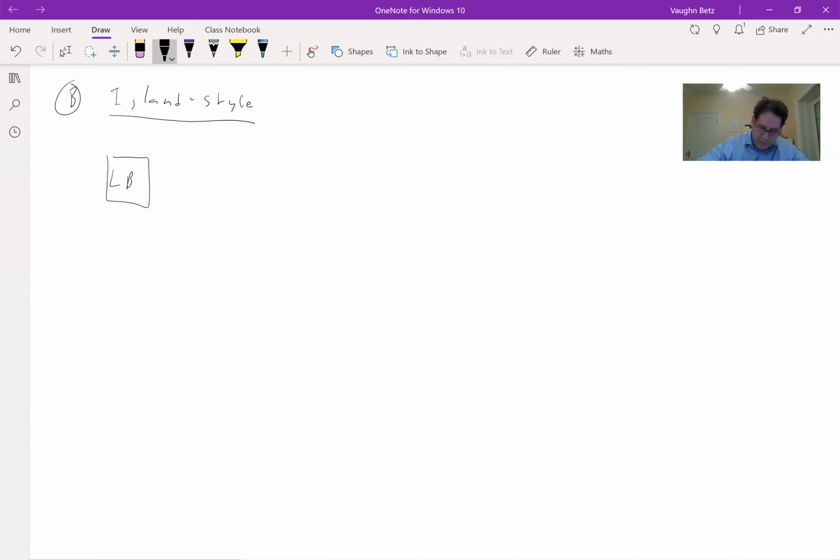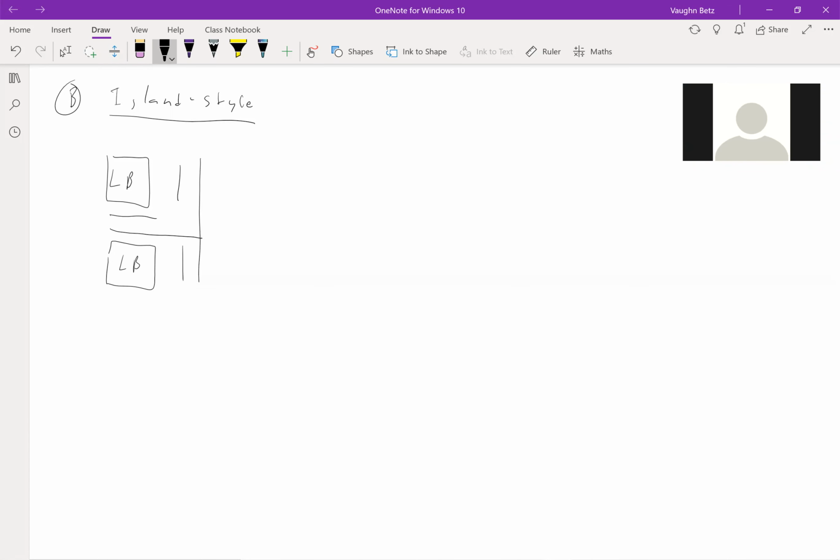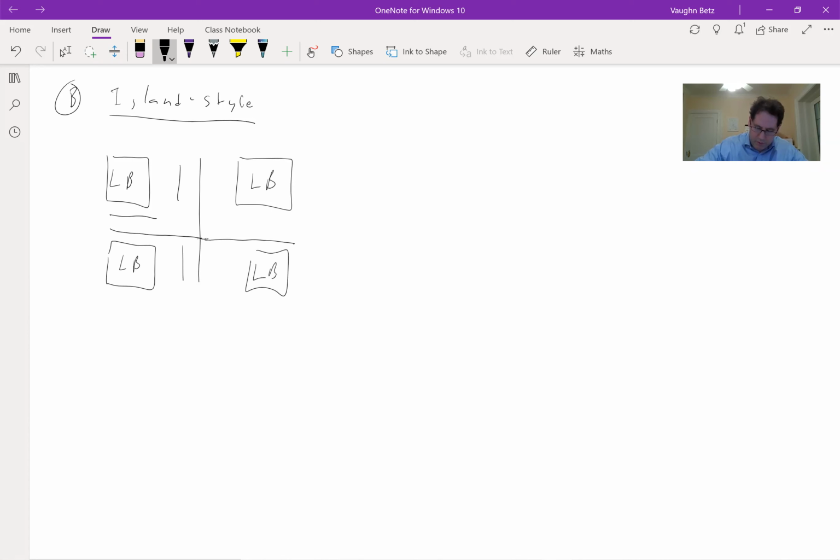We have logic blocks laid out in a two-dimensional grid, and in between them are routing tracks. These are routing wires that are prefabricated. They have a certain length before they end, and they use programmable switches to connect them together into longer routes that let you get further.